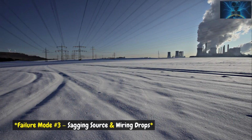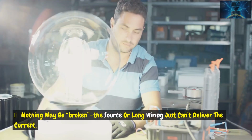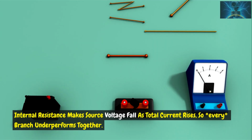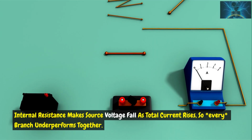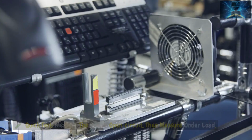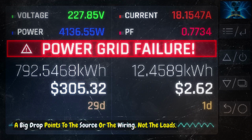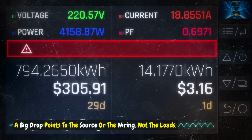Failure mode number 3. Sagging source and wiring drops. Nothing may be broken. The source or long wiring just can't deliver the current. Internal resistance makes source voltage fall as total current rises, so every branch underperforms together. Quick test: measure the source open circuit, then measure under load. A big drop points to the source or the wiring, not the loads.